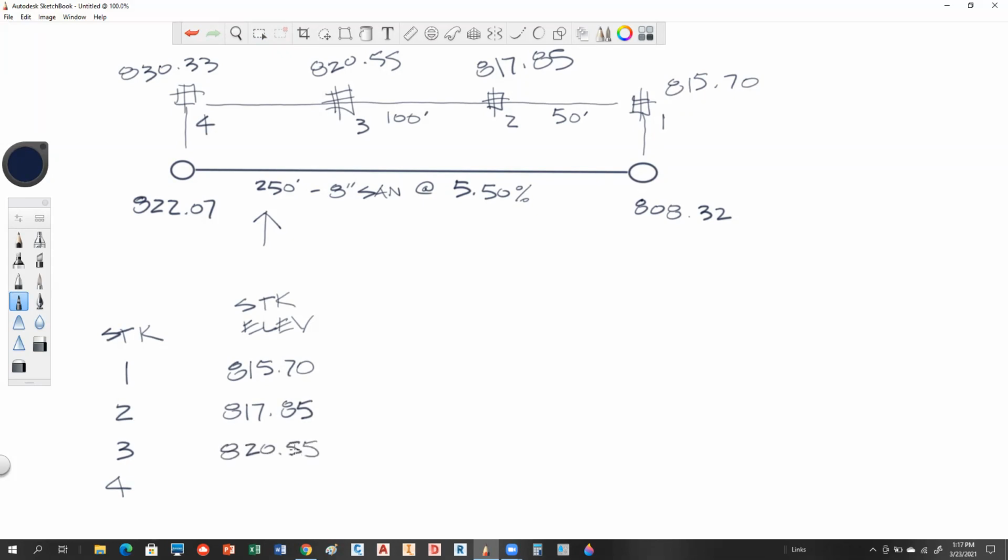Where would they come from in reality? That would come from your elevations on the ground. Not on the ground, to the prism. Well, you could do it if you're doing trig leveling, but if you're doing differential leveling, you got those somewhere, right? From either differential leveling or trig leveling. I guess that's my point, right? Does everybody understand that? Yeah, they're pre-recorded.